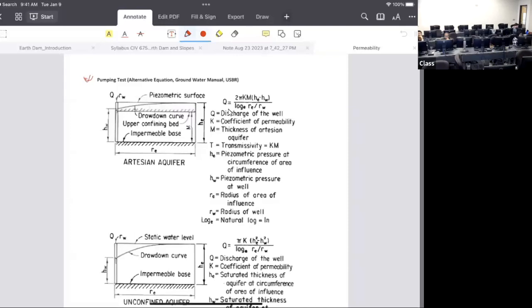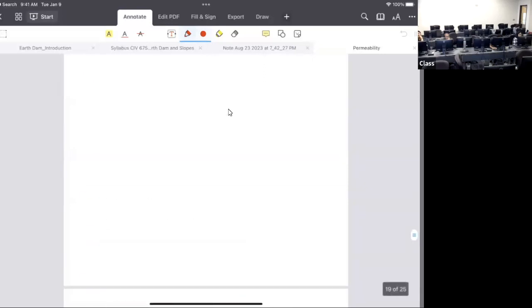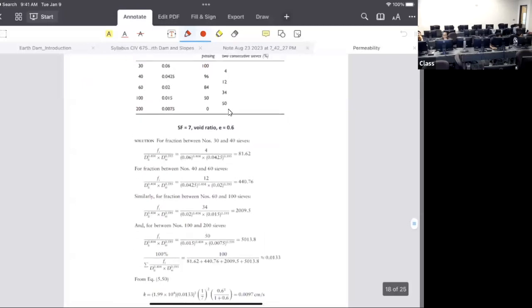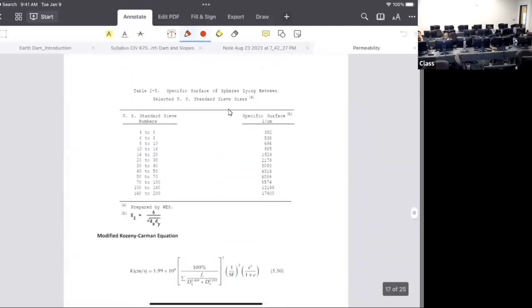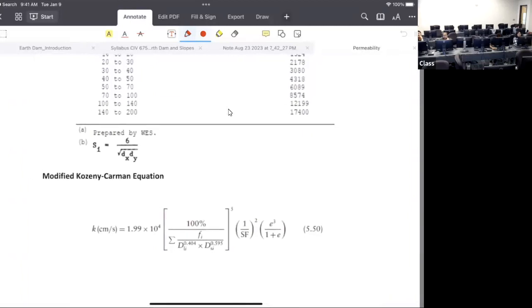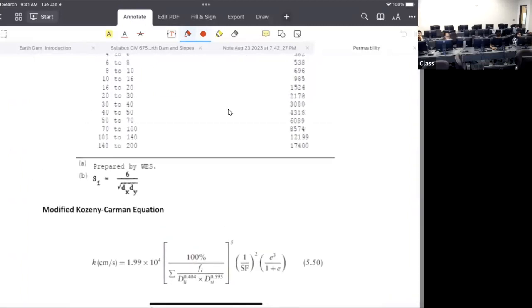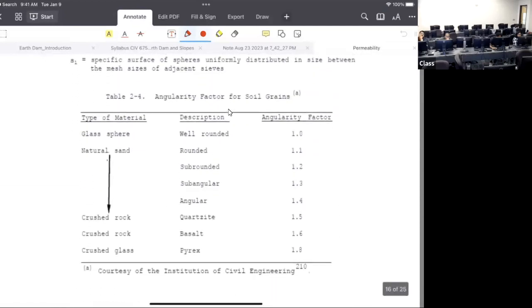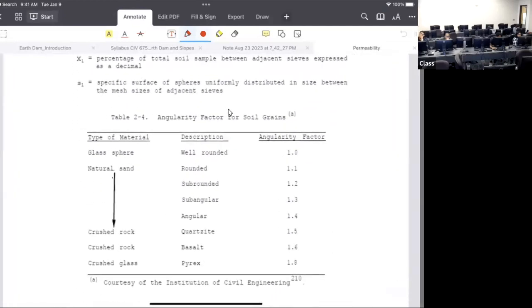No question on that. Because looking at the resistivity value, we know the type of the soil. If you know the type of the soil, then we can also find out the characteristics of the soil, whether it is sand, silt, or clay. And knowing that, there are some other ways of calculating. For example, the gradation curve. If you know the gradation curve, you can find out the permeability. There are some indirect ways of calculating the permeability from there. That's one way.